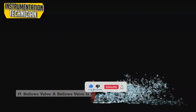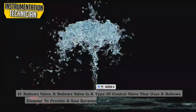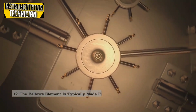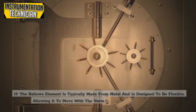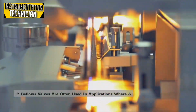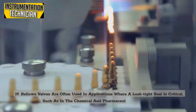Bellows valve. A bellows valve is a type of control valve that uses a bellows element to provide a seal between the valve stem and the valve body. The bellows element is typically made from metal and is designed to be flexible, allowing it to move with the valve stem as it opens and closes. Bellows valves are often used in applications where a leak-tight seal is critical, such as in the chemical and pharmaceutical industries.